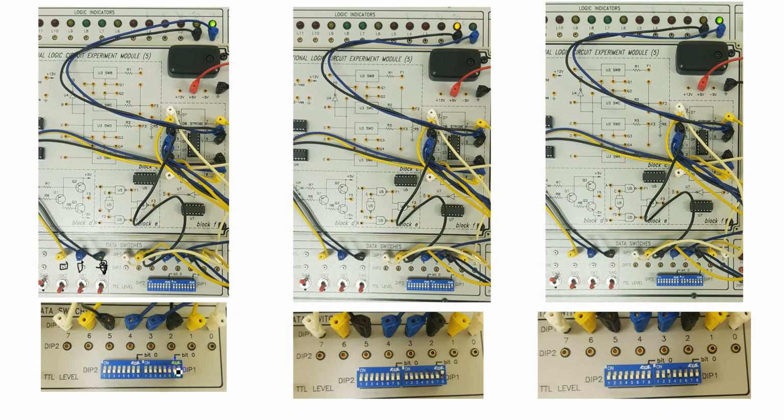What is the value of D0 here? This is your D0. The value of D0 here is 0, and you are getting 0 here. This is the complement value, so if this is 0, this will be 1. How can you verify that it is working properly? For the same selection input, if I make the value of D0 equal to 1, my Y should also become 1. So this is what we did. We made D0 equal to 1 for the same selection input, and it becomes 1 here. Obviously the complement value will be 0 here.